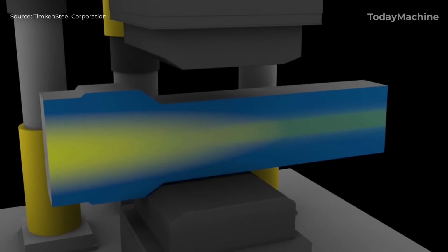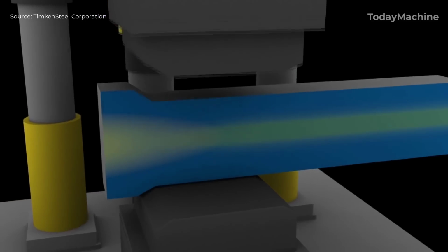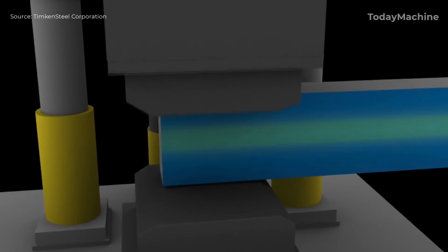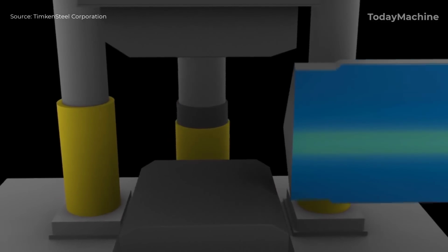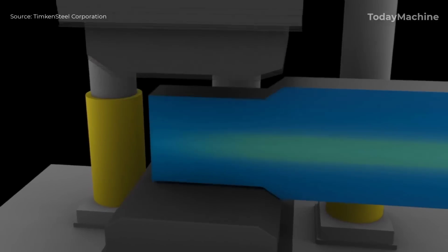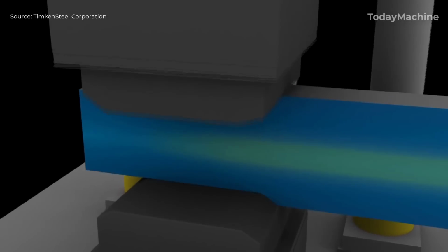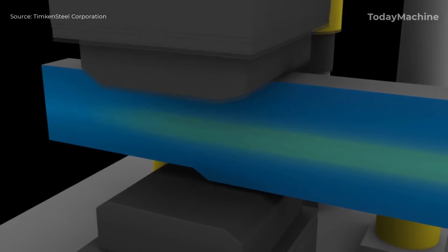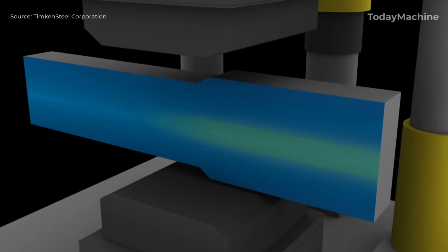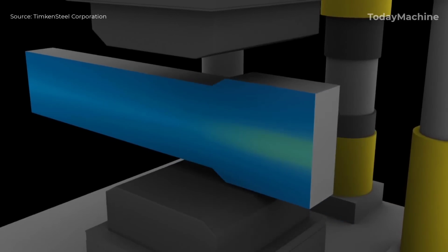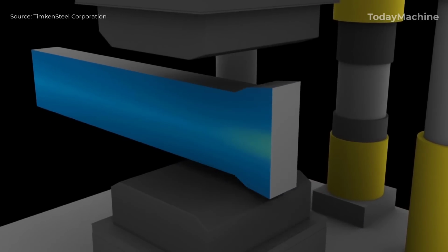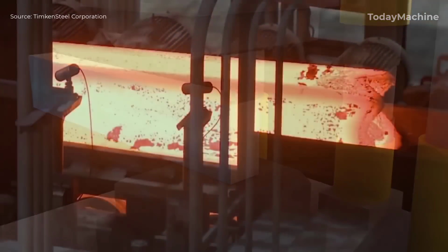This pressure is applied uniformly across the entire length of the ingot, compressing the hot metal and improving its internal structure. The forging process includes multiple passes, each contributing to the enhancement of the ingot's center soundness and strength. This step is crucial as it ensures that the final product has a uniform and robust core, essential for applications where material integrity is paramount.